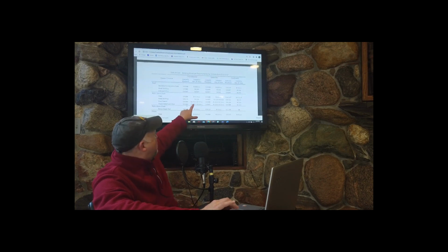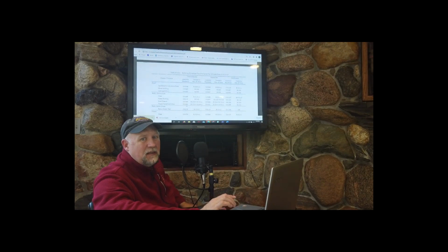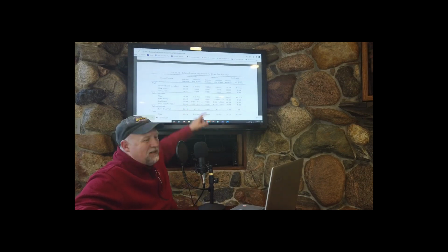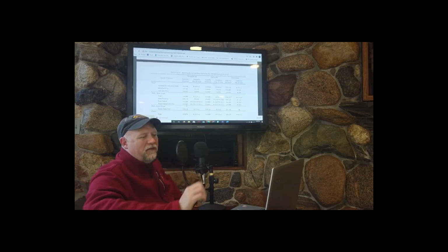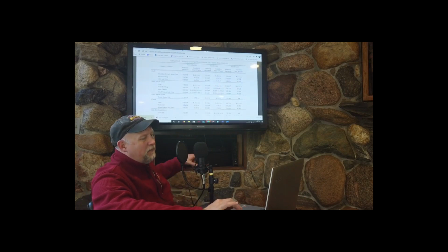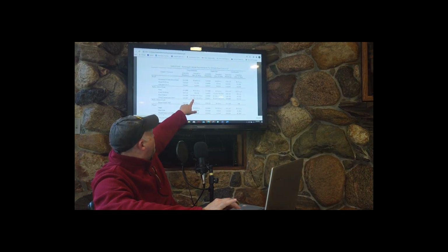And they put it this way so that it's easy for a building inspector to inspect. They can look at the face of that insulation that's between the studs and see if it's an R value of 13 or not. And then they can easily check to see if there's some rigid insulation that goes outside of the studs that's continuous at that 7.5. And they do the same thing here for wood studs as well.